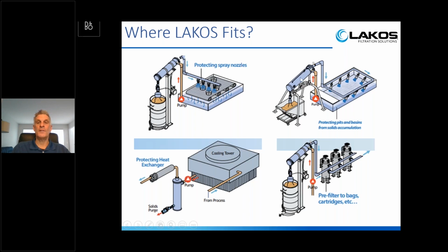Again, we concentrate all the solids out of the liquid stream and put them into the hopper in this case, and then the clean water discharges out the outlet of the separator and goes back to this header that feeds these hydro boosters. So in tank cleaning, really what you're doing is using your closed loop system and constantly turning over the tank or basin and removing the solids as the separator sees them.